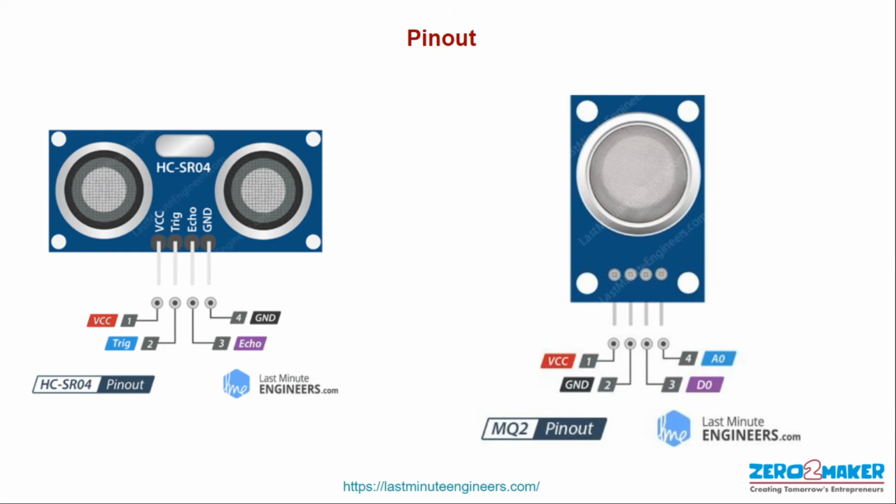So what is analog and what is digital, I will explain very simply. If you say how much the speed is, and you say it is 43, that is analog. So you can actually measure what the difference is. But now if someone asks, hey, whether the speed is 50 or not, you can say 0 or 1. So digital output will say the threshold, a trigger only, so whether the gas is there or not. But analog will say the percentage of gas detection.